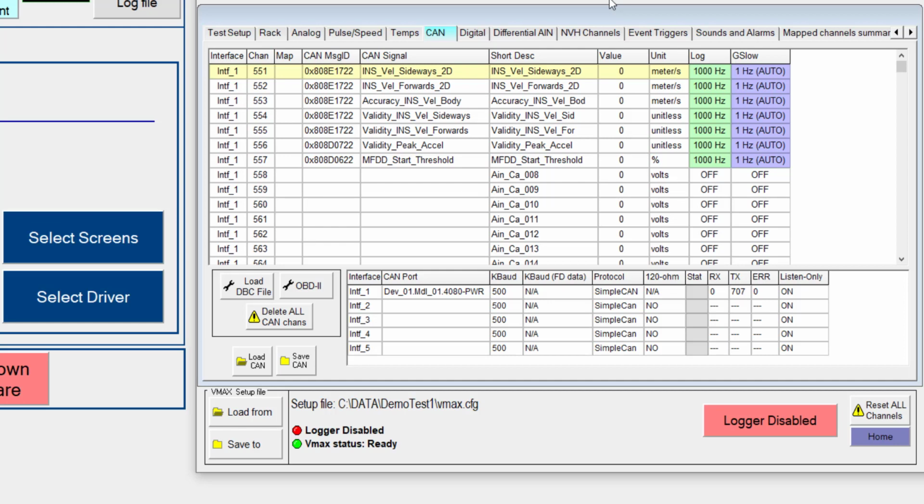It is also worth noting that on many modern vehicles now, in order to get access to the CAN bus, there may be some security measures that have to be accounted for. Many vehicles now have some type of security device between the diagnostic port and the CAN bus that would prevent any unwanted traffic from either reading or writing to that CAN bus.